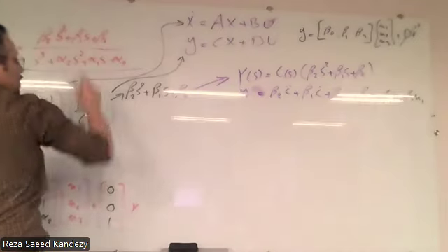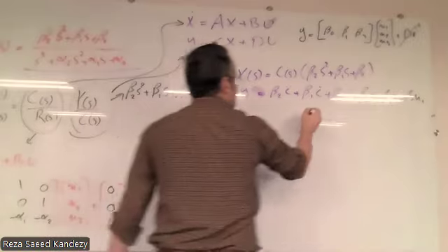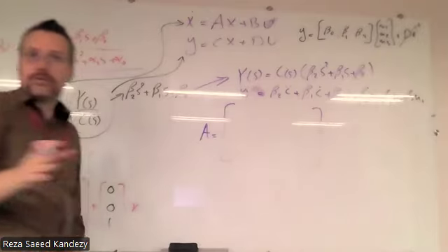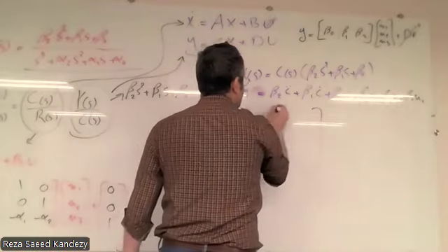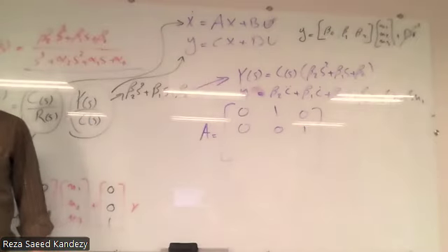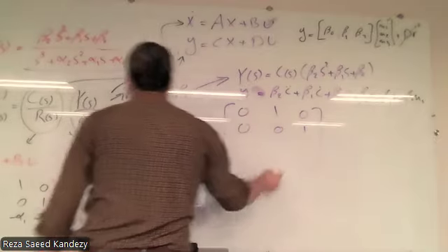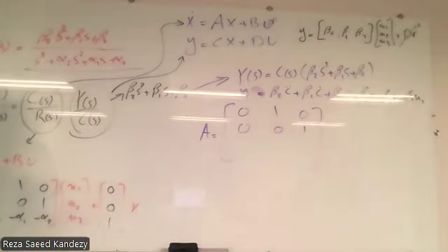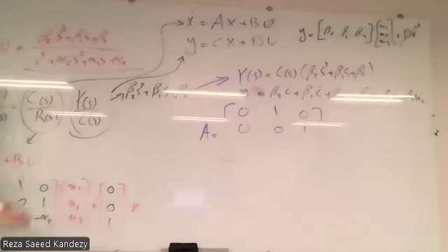Using the G(s) alone, the A matrix, the first two rows, based on our assumption and definition, is always going to be 0, 1, 0, 0, 0, 1. That's given. The third row is going to be minus all those coefficients in reverse order.